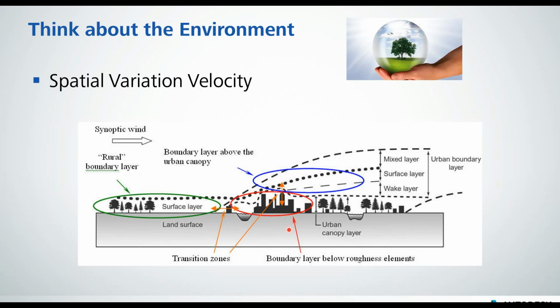The same is true for the sailboat. The wind at the surface of the water is significantly less than at the top of the mast. That's where you get your fractional rigs from, some of the sail design, all try to capitalize on what the expected velocity profile is for the sailboat from the height of the water. All right, so we have this spatial variation boundary condition. Can be done for the velocity, for the pressure, the temperature. Basically point it in a direction and then give it a profile curve to say the velocity is lower here, higher here, or whatever gradient exists for your model.